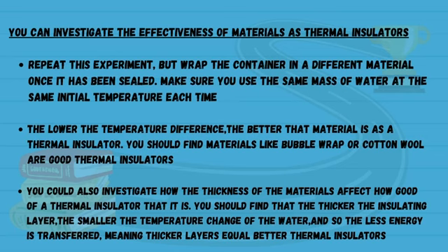Repeat the experiment, but wrap the container in a different material once it has been sealed. Make sure you use the same mass of water at the same initial temperature each time. The lower the temperature difference, the better that material is as a thermal insulator. You should find materials like bubble wrap or cotton wool are good thermal insulators.